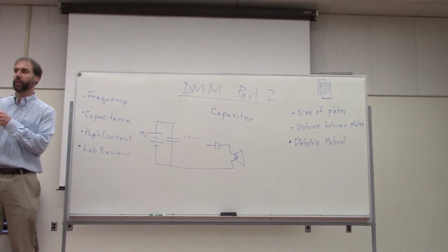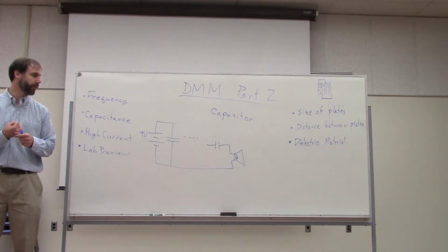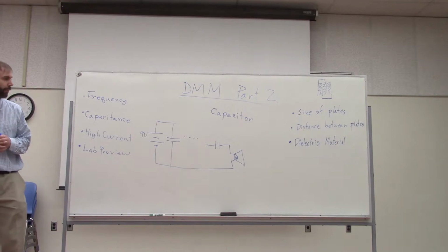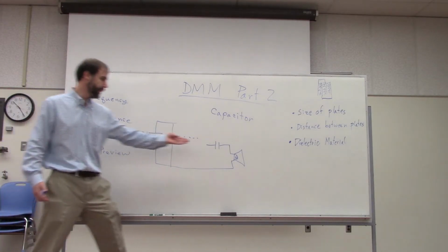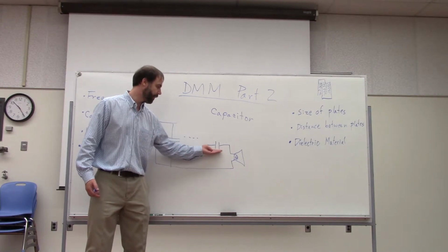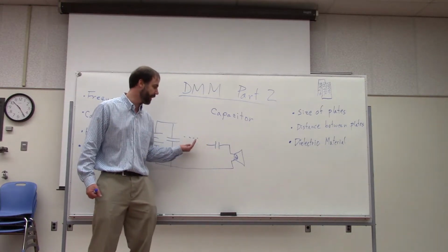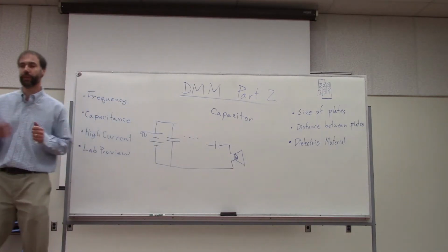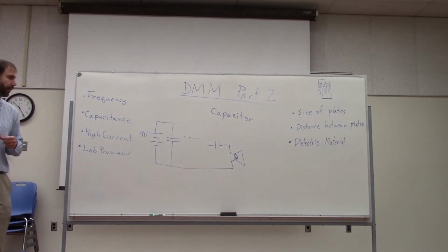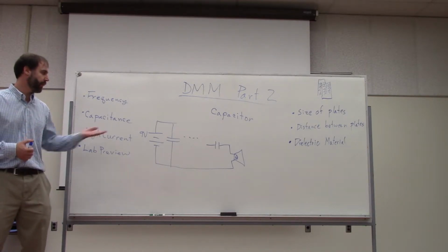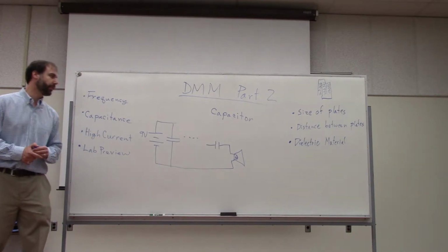So the wire would be heating up, and it could damage the speaker, and also be draining our battery. So we want to block out DC signals from our speaker. So putting the capacitor here acts like a filter and allows the AC to go through, but blocks out the DC signal. So that's another use for capacitors. And there are other uses as well, but those are a couple of typical examples.